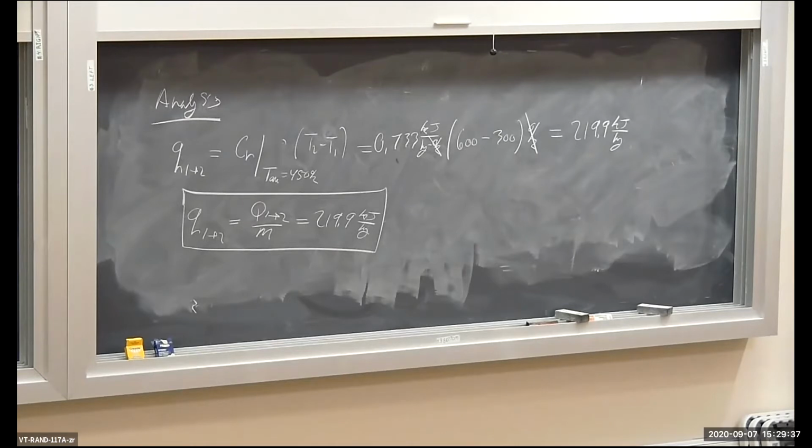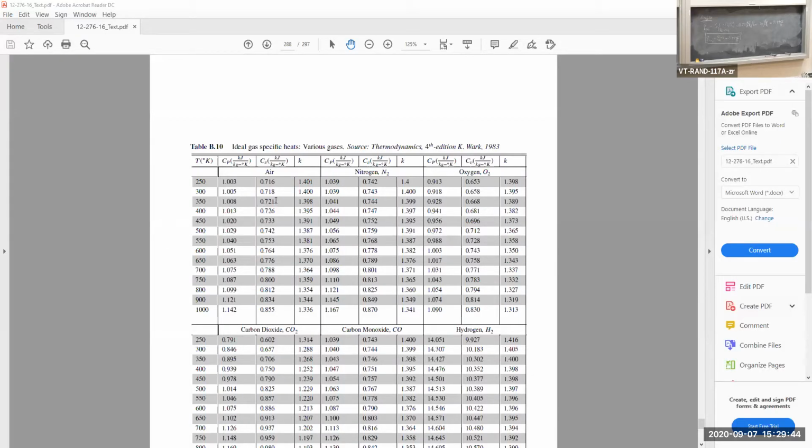And if you look at the tabulated values for specific heat, they don't change that much. So here, let's go back and look. Specific heats for constant volume process, again, 0.721, 0.776, about a 0.055 kilojoule per kilogram degree Kelvin change. About 10% variation between 300 and 600 degrees, about 10% or less. So we would expect our heat transfer calculation to be within 90–95% accuracy.